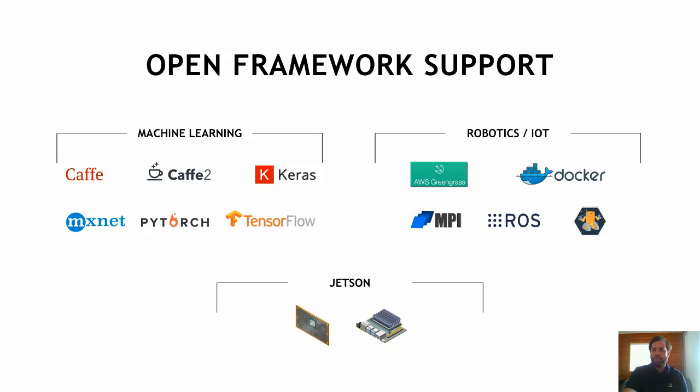You can take your existing Python code using TensorFlow or PyTorch, for example, install those same frameworks on any Jetson, the full versions of them, and run that same code there. Really handy, and with the level of compute available from the GPU, you don't need to use reduced or limited versions of the frameworks like TF Lite for lower-end embedded processors or custom chips that only support a fixed set of network layers. These all have the ability to work with TensorRT for even better inferencing performance too.